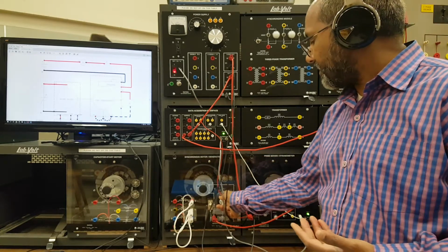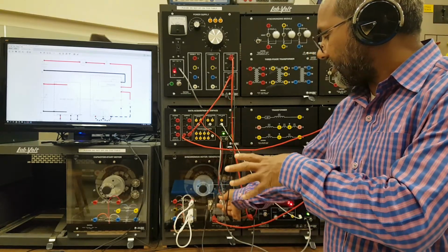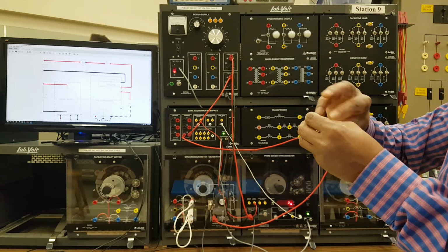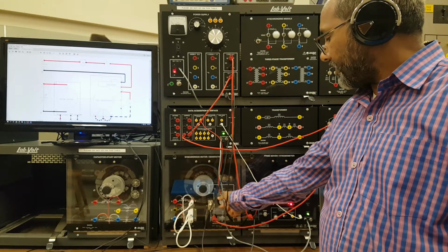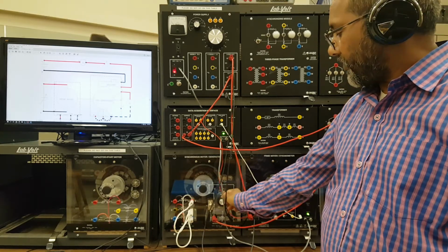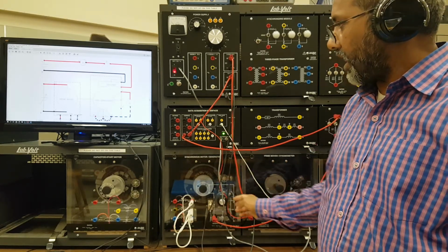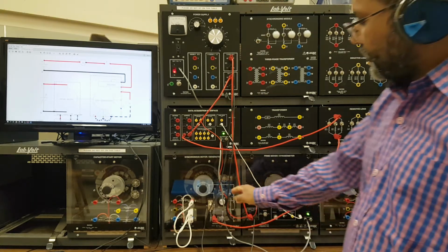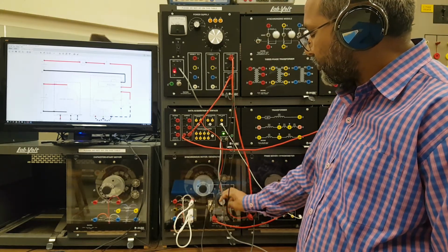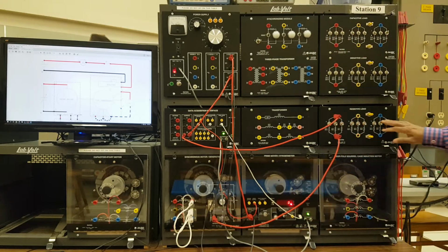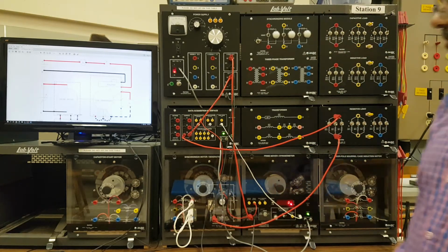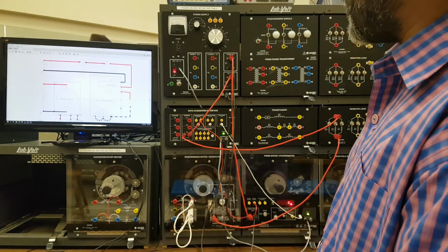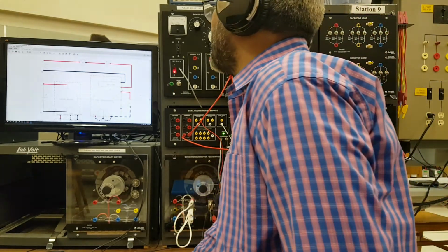And here, because it's a smooth variation of the resistance, there is a pot with a number of turns, and when we change the knob, the field current changes smoothly. I will show you in a moment when we do the experiment. So this is for the smooth variation, and this is for the coarse variation, meaning more discrete steps.